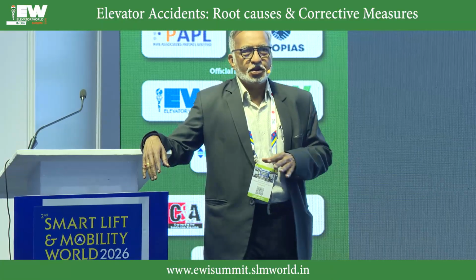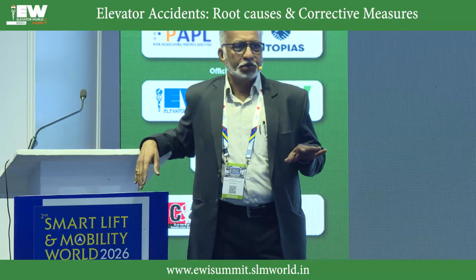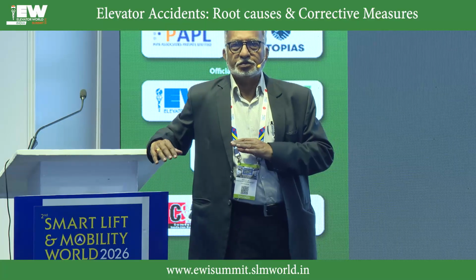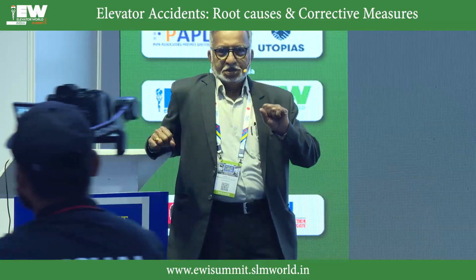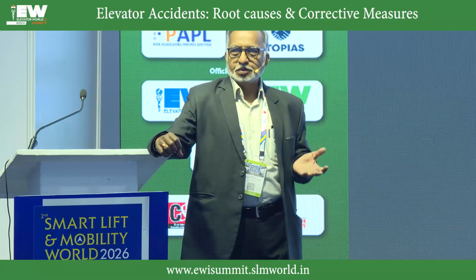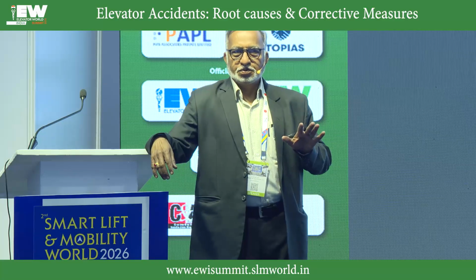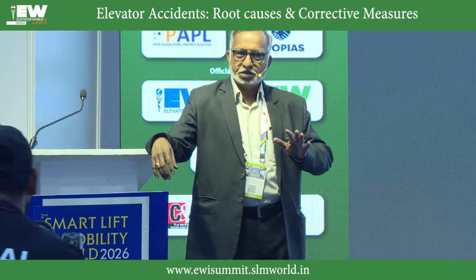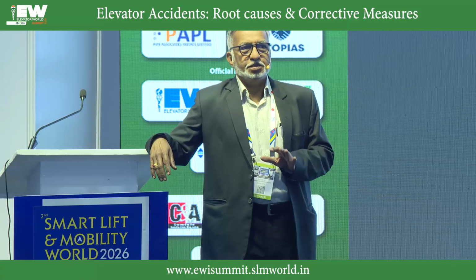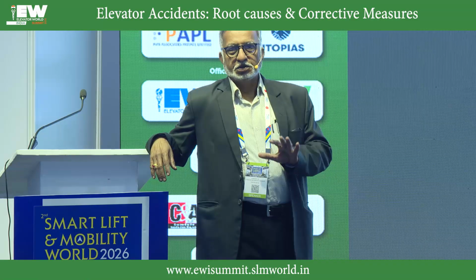Rope broken, lift fall. There is no chance of a lift falling because all the ropes break. There are minimum 3 ropes, and maybe for low-speed lifts the ropes may increase from 3 to 4, 5 or 6 also. Breaking of all ropes at a time is next to impossible. The lift rope has a factor of safety of 8, which means it can take 8 times the load.